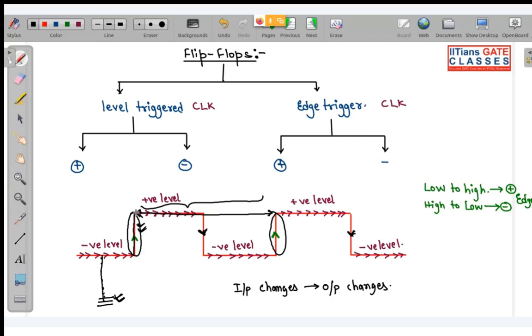If the flip-flop encounters a positive edge at this point, then it will change its output if this input has been held constant from this time to this time. After this precise moment, your output will be held until the next positive edge.